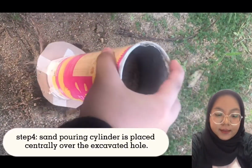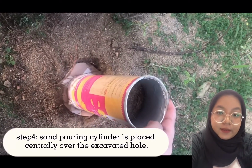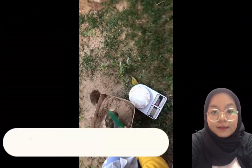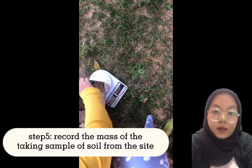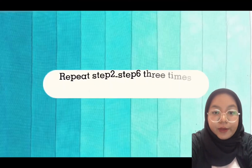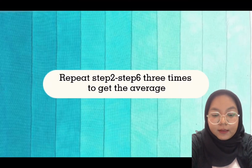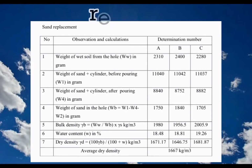Step number 4, the sand pouring cylinder is placed centrally over the excavated hole. Step number 5, record the mass of the soil sample taken from the site. And lastly, repeat step 2 to step 6 3 times to get the average.